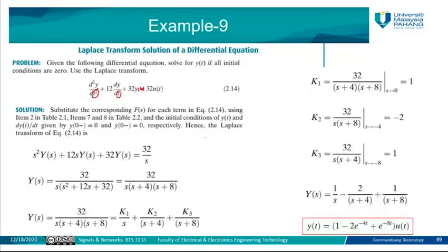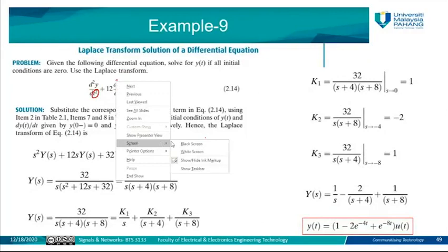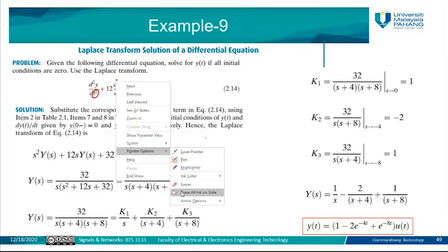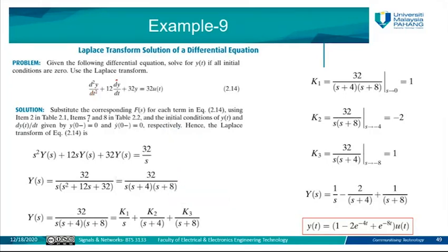Okay, so how do we write this equation again by using the Laplace? You just replace each derivative by s. If you have the first derivative, it becomes s. If you have the second, it becomes s squared. If you have the third, it becomes s cubed and so on. So you rewrite the equation like this. It is s squared, then y(t) here, we do not write it, but by default a small letter means it is y of t. So y(t) here will be converted into Y(s), capital letter, with the s operator.